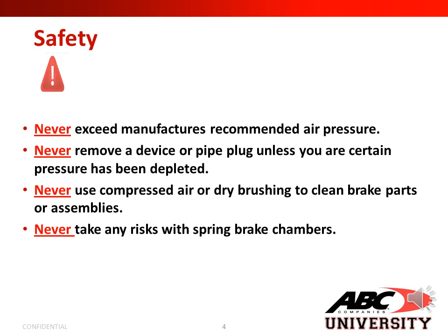Never exceed manufacturer's recommended air pressure. Never remove a device or pipe plug unless you are certain pressure has been depleted from the system. Never use compressed air or dry brushings to clean brake parts or assemblies. Never take any risks with spring brake chambers.